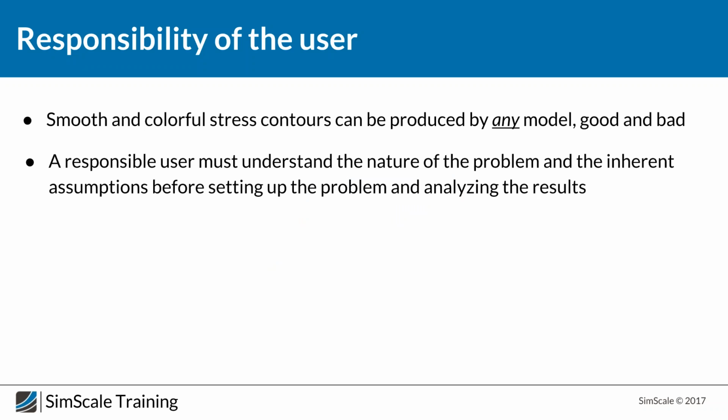Your responsibility as a user is to really make sure that you understand the problem and that your assumptions are right and you really follow the right procedure to set up the simulation, because it's very easy to create a smooth and colorful picture with nice stress distributions. But this can be produced by any model or any tool, independent if it's good or bad. Actually, you can even create them with Photoshop. This is also something which I saw during my career, engineering departments who had a simulation tool, but were not able to use it and were just tuning the results like in Photoshop. And that's not what simulation engineering is about. So your responsibility is to make sure you're using the tools the right way.